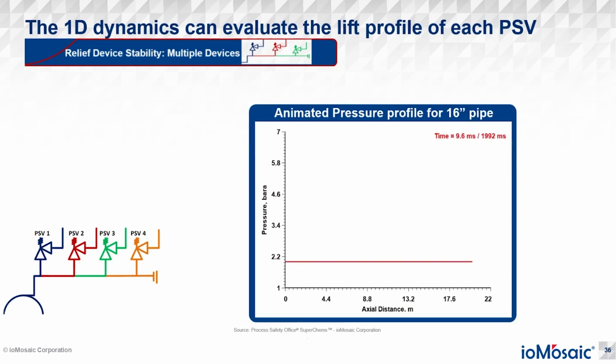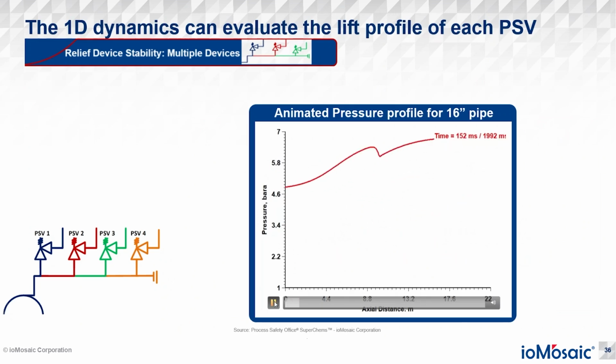What's interesting is we can also see this in the animation. If I play the animation, I can see they open quite quickly, but they go up and down, and the pressure waves and the opening of the PSVs are all quite in sync. Now, if I pause and freeze the animation here, you can see the little bumps, and this is when all of the PSVs start flowing material out.